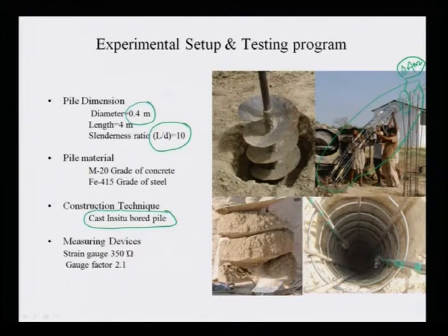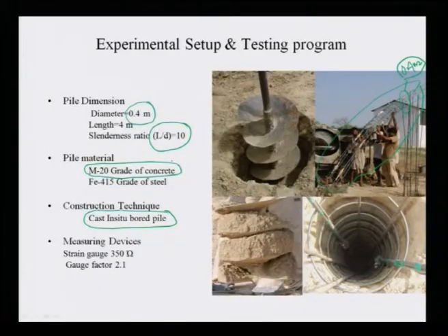Once it has been pushed inside the ground, what will happen? You prepare concrete, M20 grade concrete. Then you pour this concrete inside, so that it becomes the reinforced concrete of the pile. So, why is it called a cast in situ bored pile?